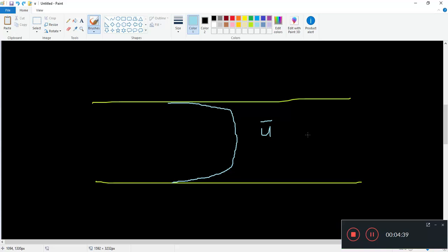So remember we have a Reynolds transition, where if we have a Reynolds number equal to rho times velocity times d over the dynamic viscosity, and the velocity is low enough, the regime will become laminar.